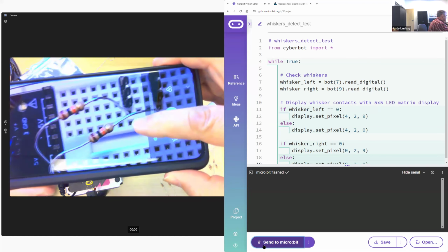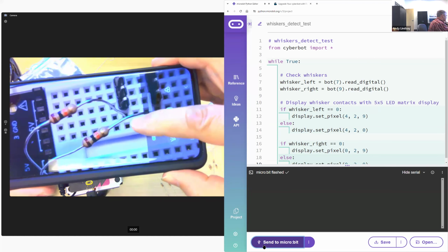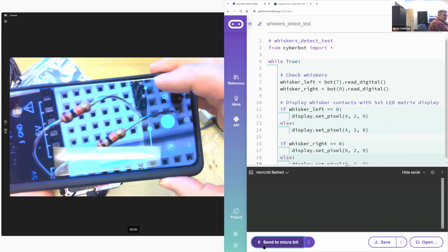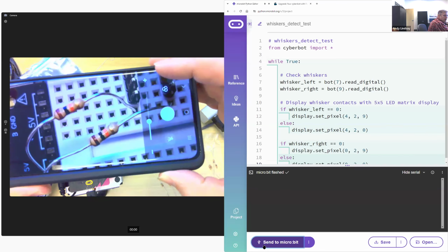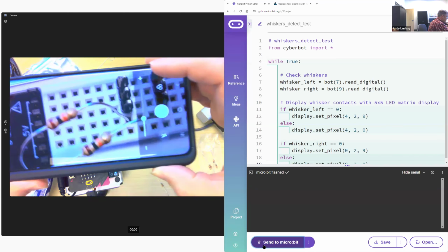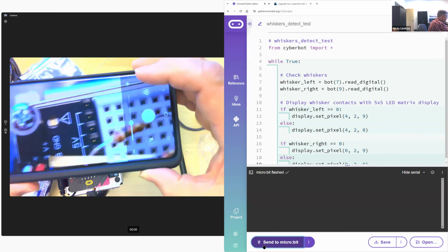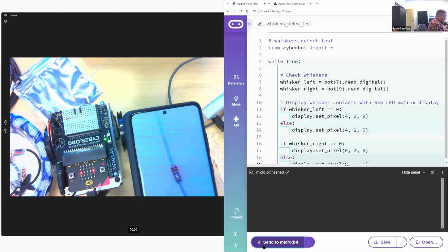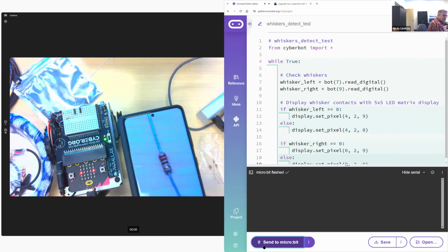For selecting resistors, it's nice to be able to zoom in, and you can very clearly see the color codes usually on your cell phone using the nice magnifier feature. And so here are my red, red, brown resistors.